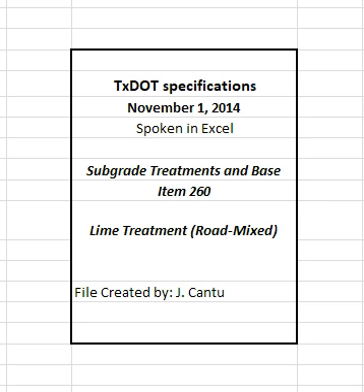4.8 Curing. Cure for the minimum number of days shown in Table 2 by sprinkling in accordance with Item 204, Sprinkling, or by applying an asphalt material at a rate of 0.05 to 0.20 gallons per square yard as directed. Maintain moisture during curing. Upon completion of curing, maintain the moisture content in accordance with Section 132.3.5, Maintenance of Moisture and Reworking, for subgrade, and Section 247.4.5, Curing, for bases before placing subsequent courses.